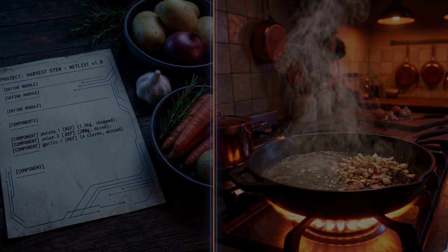The FPGA silicon surface is a grid. Hundreds of thousands of configurable logic blocks, CLBs, arranged in rows and columns. Each CLB contains a few LUTs, a few flip-flops, and a few multiplexers. In the placement stage, Vivado decides exactly which cell on this grid every single netlist gate will occupy. Of course, this placement is not random.